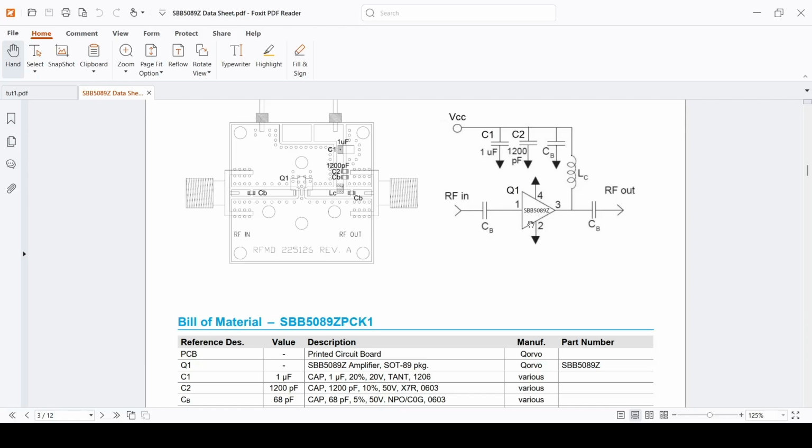So using those S parameter files, we know what the input return loss of the amplifier is, which is called S11, and based on that we can design the whole circuit. We can know S21 of the amplifier, which basically is the relationship of output to the input, or in other words, the gain of the amplifier, or S22, which is the matching to the output, right?